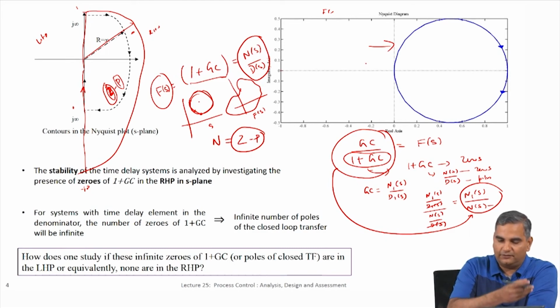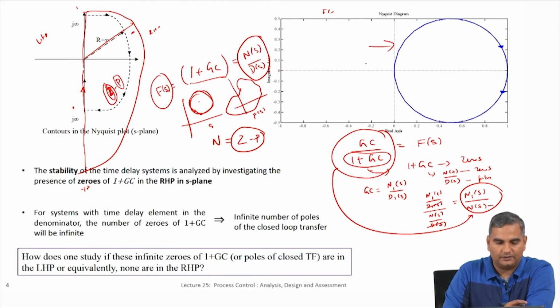That is a conversion from whatever we saw in the previous slide to a control idea, and the key insight is we know how to characterize how many zeros and poles there are, in terms of the difference Z minus P inside a closed contour, by looking at the number of encirclements around the origin in the F(s) contour.